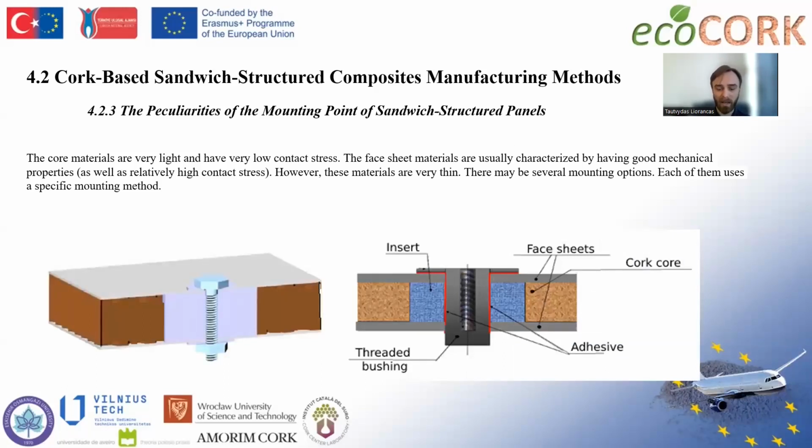A very similar strategy is used when you have to attach your sandwich panels with bolts. Then you need to install an insert during the manufacturing process. The insert will be able to withstand the high local loads that appear in places that are bolted.